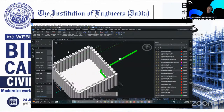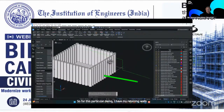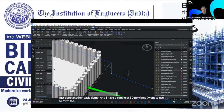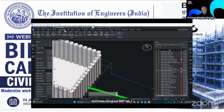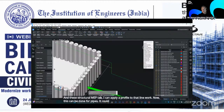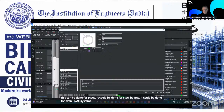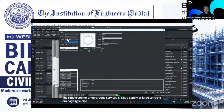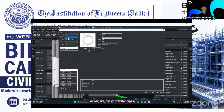So for this particular demo, I have my retaining walls and my piles that I've just done in the other basic demo. And I have a couple of 3D polylines I want to use to form the basis of my pipes. In the structural MEP tab, I can apply a profile to that line work. Now, this can be done for pipes, it can be done for steel beams, it could be done for even HVAC systems. The simple one for underground services is, say, a supply or large concrete drainage type pipe, like my stormwater pipes, for example, or my sewer pipes.